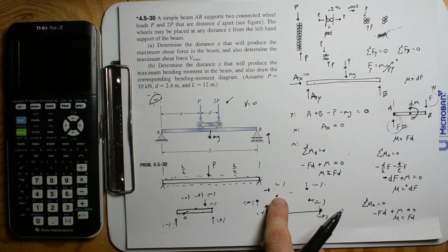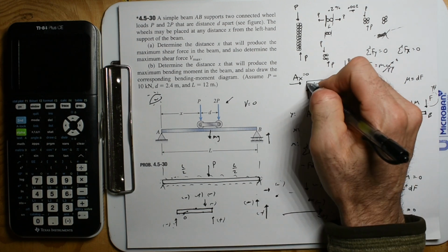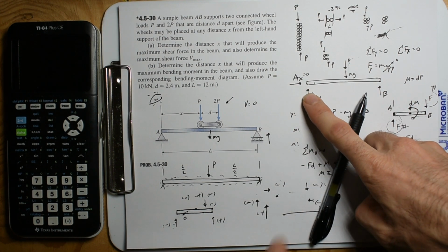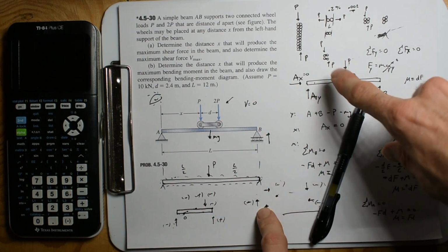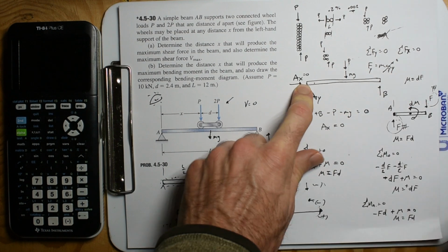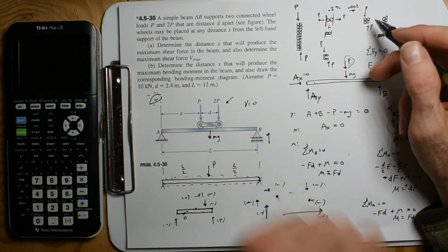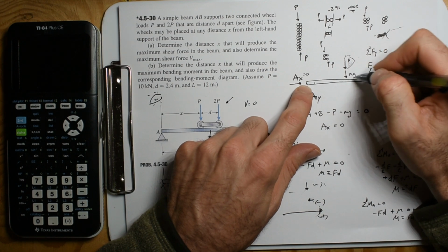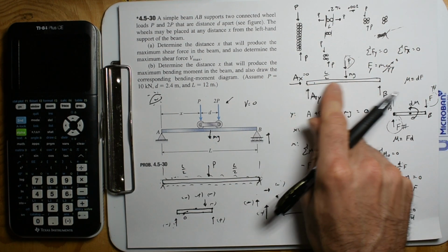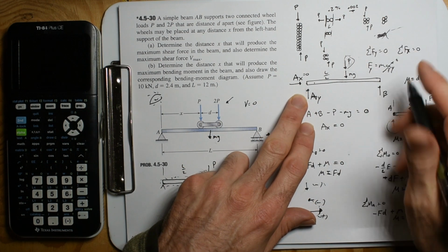Because then you can pick any point on here. And you can pick a point where it's just like, if I pick the point right here, these forces going through that point aren't causing any moment. So that's a great place to pin, because now I can see that these two forces, mainly the force that we're applying, is causing a torque, but that torque is only half the distance away, and then so this has to be applying a torque.